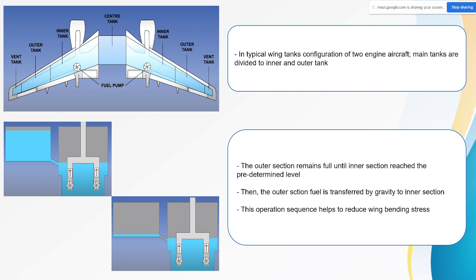This is installed to dampen the movement of the fuel, because when the plane is moving, so does the fuel. Fuel will be moving because there is space above the fuel in the tanks. So to reduce the impact of the movement of the fuel, we place a barrier that separates the outer tank and the inner tank, to dampen and reduce the effect.